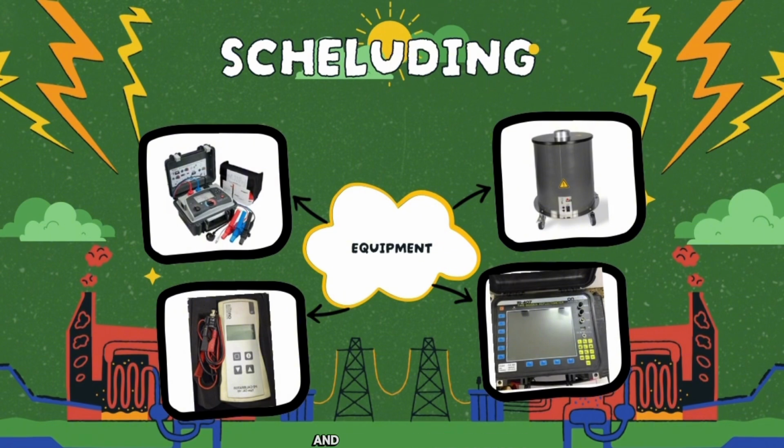I'm sorry, the TDR is at the right bottom, and the next equipment is the partial discharge calibrator at the left bottom. This is our measurement baseline tool. Its function is to inject a known precise charge packet into the cable network prior to testing. This calibrates our sensor for signal attenuation over long distance and ensures the tiny partial discharge we detect later are accurately quantified in picocoulombs.